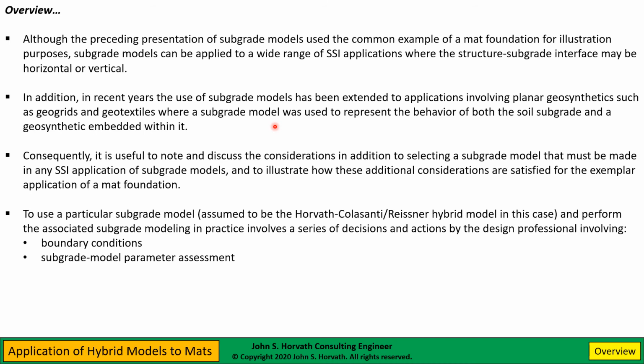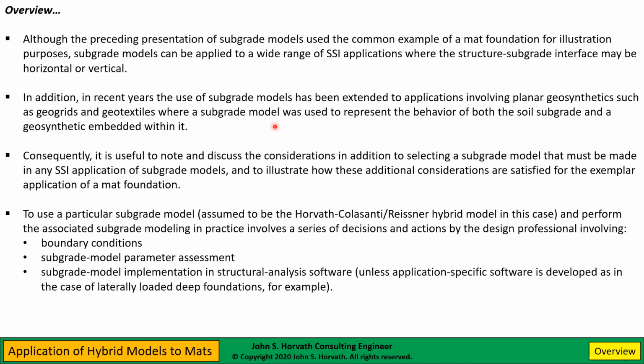You need to be able to assess the model parameters, obviously, and you need to implement them in structural software, unless, for example, you're developing some application-specific software. And for example, they've done this with laterally loaded deep foundations. I mean, there are commercial software packages that just use p-y curves to solve laterally loaded deep foundations. But if you want to use this in more general structural analysis software, you have to do a little bit more work.